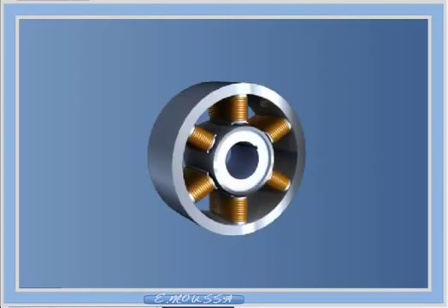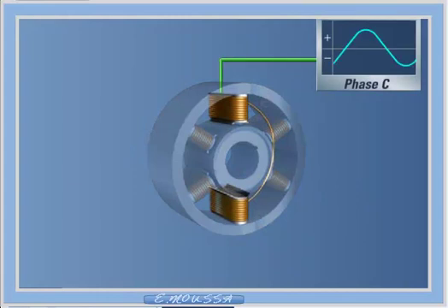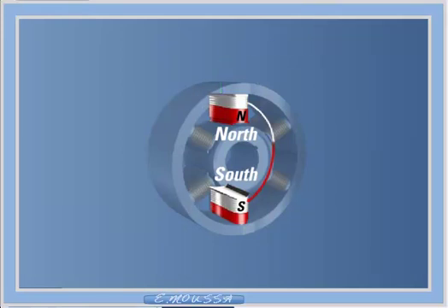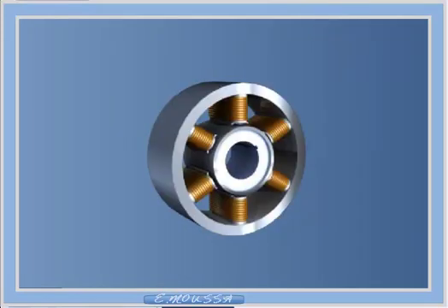The electromagnets in each phase of this two-pole motor are wired such that when current flows through one pole, or electromagnet, it flows in the opposite direction through the second electromagnet, or pole. For each phase, the resulting magnetic fields, and hence poles, facing the center of the motor are reversed as illustrated. We have labeled the electromagnets or poles in each phase as shown.